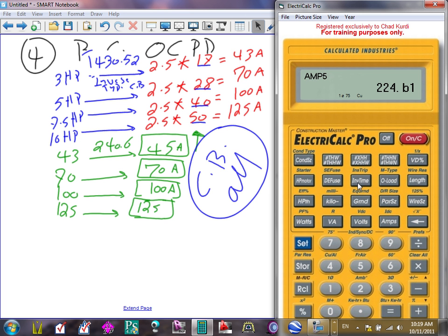I will be doing 3 phase the same way as we go through. Any question? Everybody knows how. So now, Phil, I'm doing it in segments, but in reality, you put the horsepower and the voltage, and from that you can find the conductor size, you can find the overload, and you can find the overcurrent protection device directly from the same calculation, just by hitting a couple of buttons, and you can change your mind as you go. Okay, so we verified that.